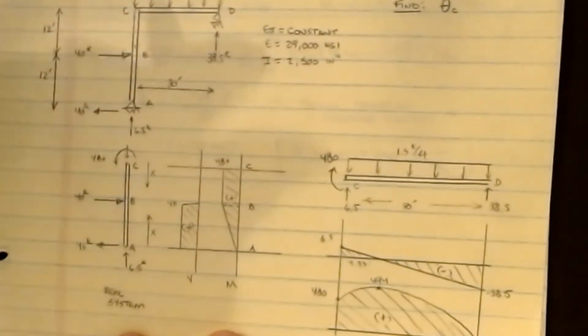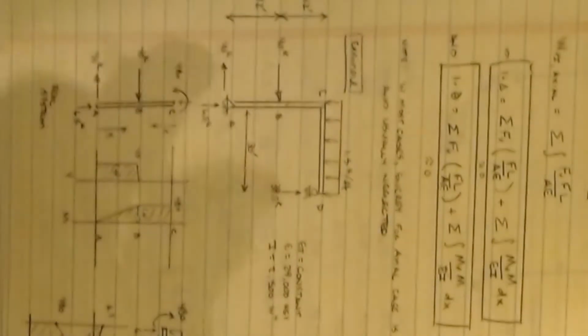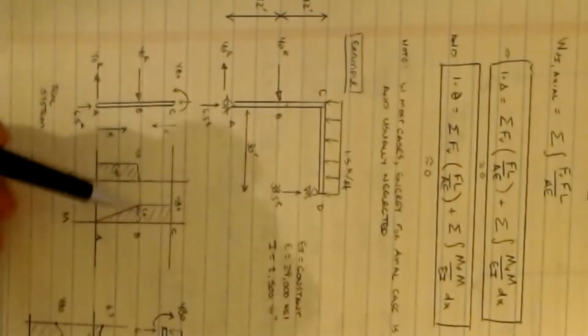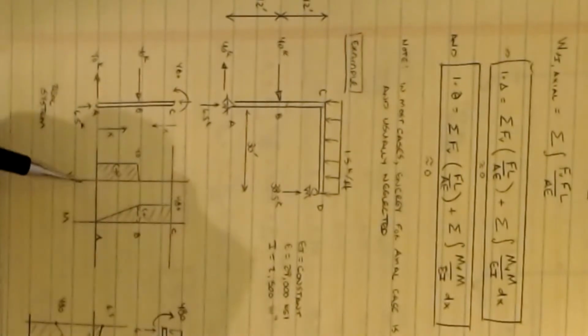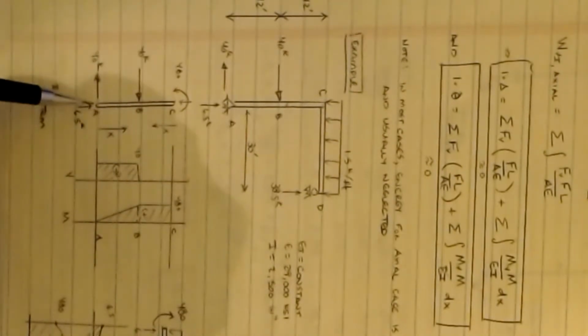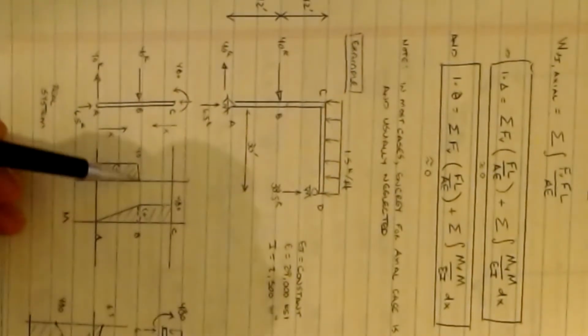Now, if I draw the shear moment diagram, we're going to take this picture and turn it 90 degrees. And you can see that this is just like drawing a shear moment diagram for the beam that we had. So if we look at our particular directions, if I do my shear, we're going to the left on the shear this way. So then I'm going to go up 40 kips. It's constant over to the point load and then comes back to 0.